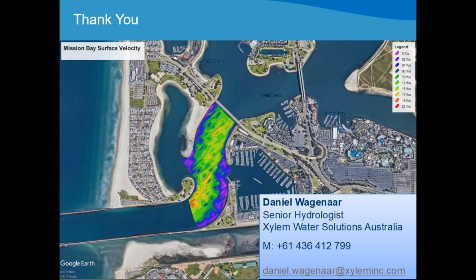But if one or two of the beams are moving away from the group, then you know you have beam separation, and you will have to stop the measurement, clean the instrument and continue. If that still persists, then you will have to think about lowering the instrument. RiverSurveyor Live does supply warnings in the QA box where it will tell you there's beam separation occurring. If that happens, you need to stop immediately and either clean the instrument or lower it deeper in the water.